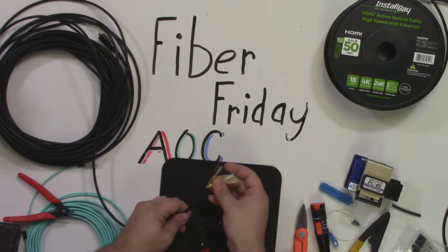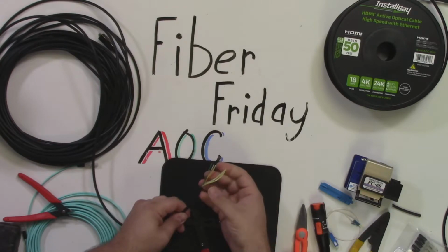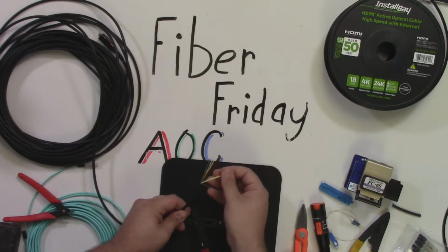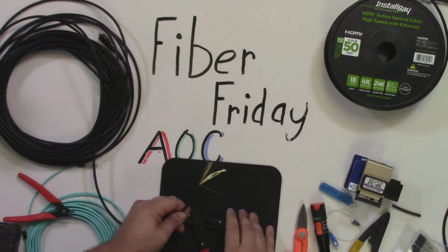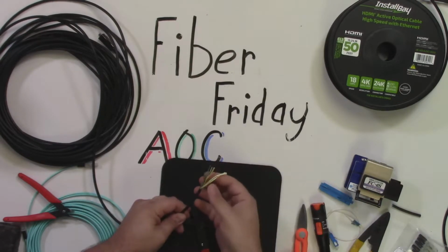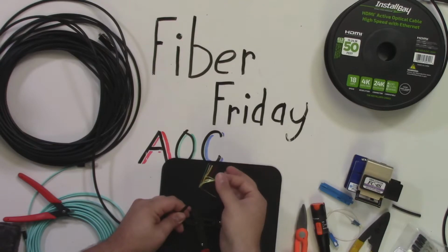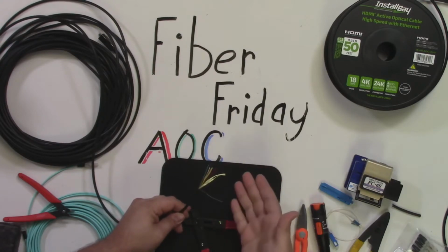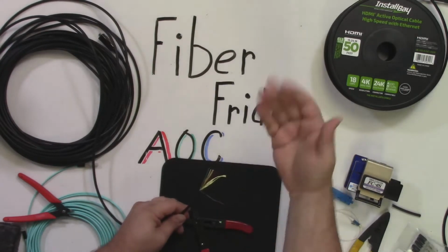Now what you do have for strain relief in here is this Kevlar stranding inside there. That's that kind of yellow piece there. Now, normally what you would see inside of a regular bulk wire, or the bulk fiber, is this Kevlar, because this is what you're going to use for strain relief when you actually terminate the cables. You're also going to use that when you're pulling the wire through the wall.